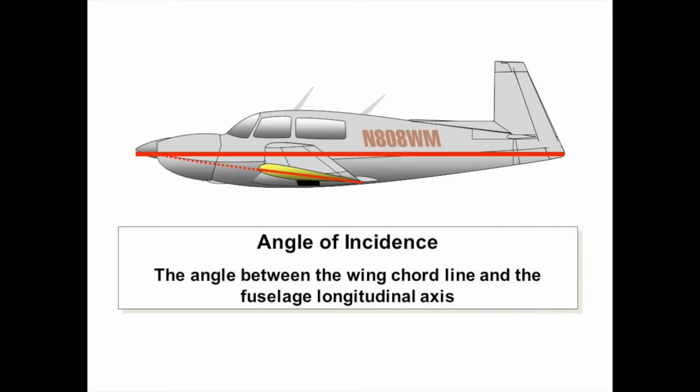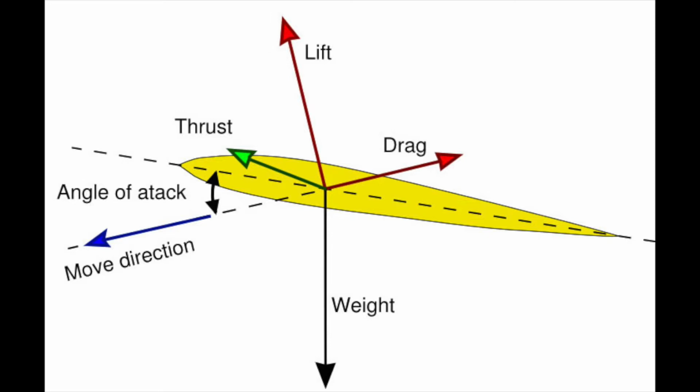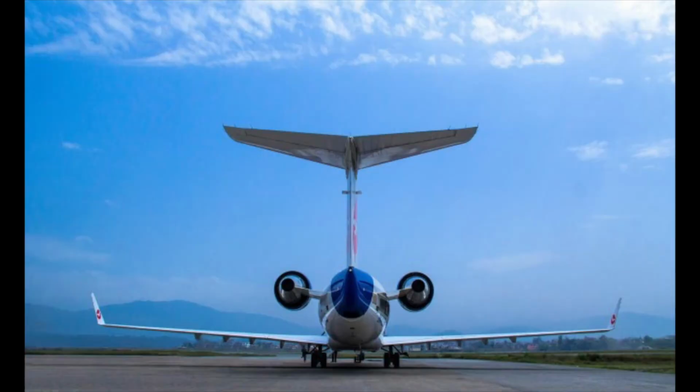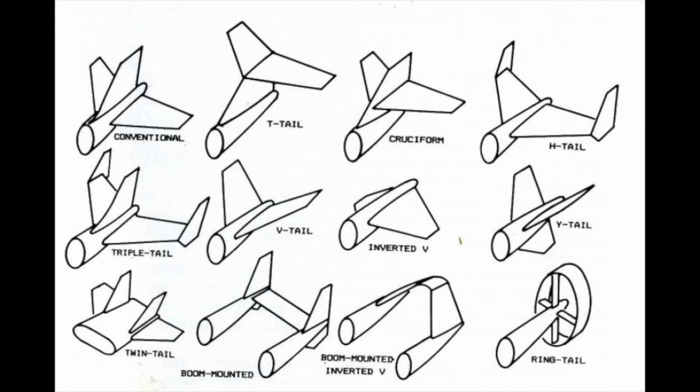The main wing with a conventional aerofoil profile will have a small incidence, which is the angle the wing meets the airflow and gives constant lift. Without the tailplane, the aircraft would climb. So most aircraft have a tailplane with a small negative incidence to counterbalance this. The whole assembly, tailplane and vertical stabilizer, are known as the empennage. There are many different configurations of those.